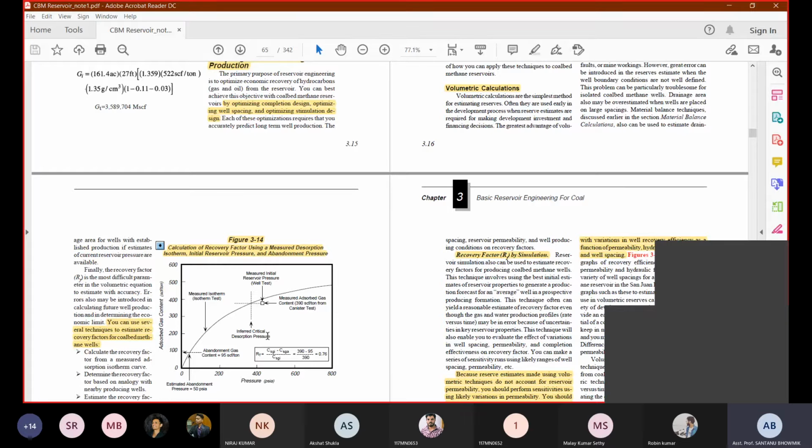First you have to reach that much pressure, you have to go down from this pressure zone to this pressure zone, so that you reach the critical gas dissolution pressure of the particular gas of the particular reservoir. And then, once the critical dissolution pressure is attained, when you further reduce the pressure of the reservoir below this critical dissolution pressure, only then will the gas production start. Okay. And again, the gas production will be possible only up to the point of abandonment pressure.